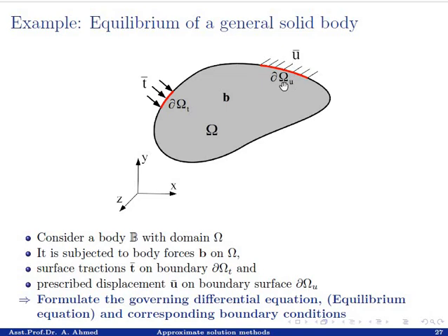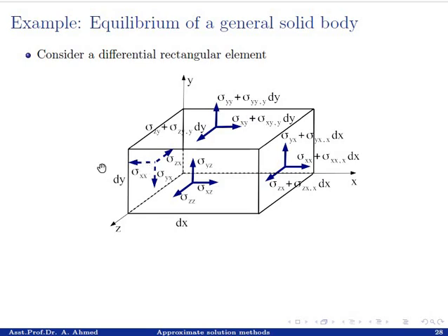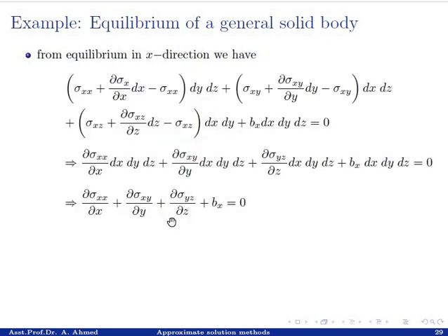Again, in order to develop the governing differential equation, just take a differential element. If it's a 2D body, take a 2D element. If it's a 3D body, take a 3D element and then represent forces on that differential element. And then apply the equilibrium condition on this differential element. We have already done it in the previous lecture.